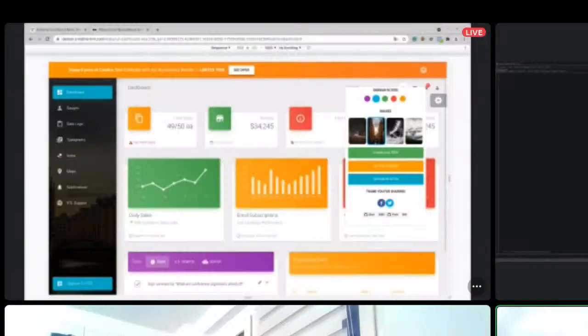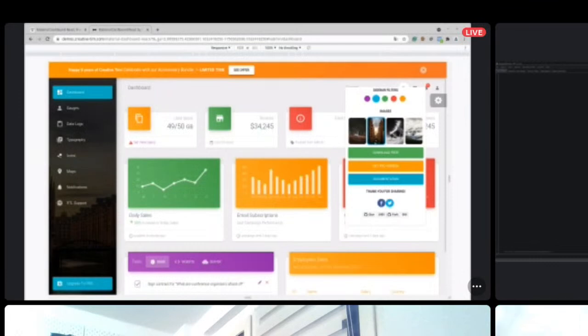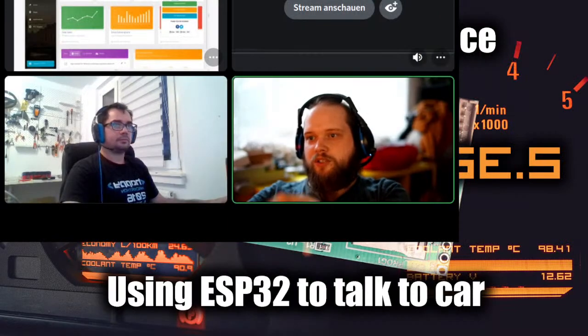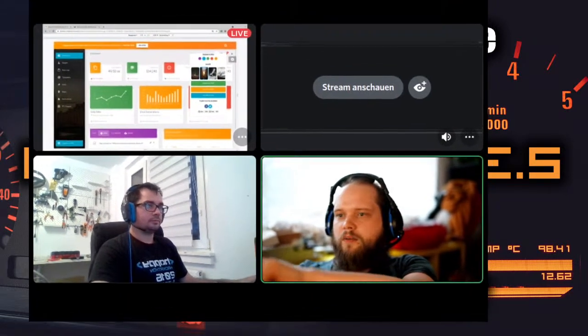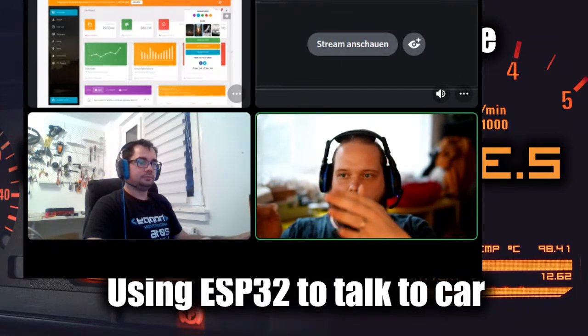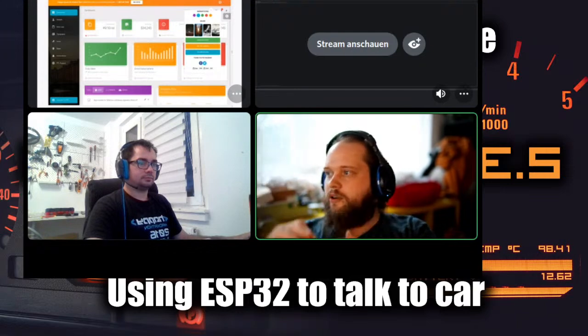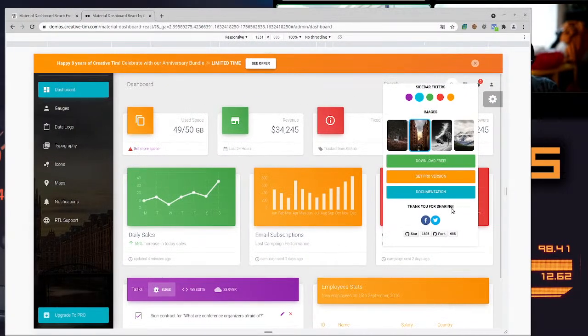More or less, yes. Well, you can still view logs and see, oh, my highest coolant temperature was this. But if you compare engine load, RPM, and coolant temperature, you see that it makes not much sense. But if you have a hotspot like on here, you see up there in the down part, it's not shared on the screen, I think, but more or less it works like this. So you can see, oh, at high RPM I have some coolant going up. So you just use it. That's a tool to analyze logs, basically. Okay.